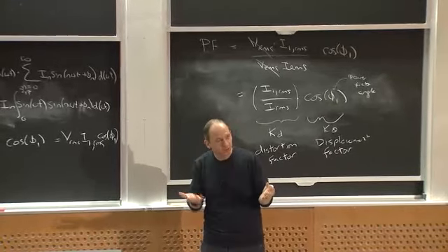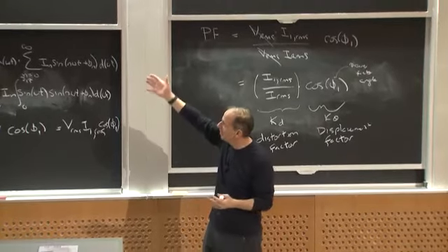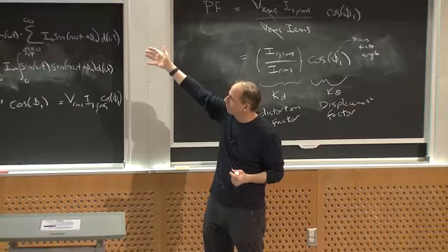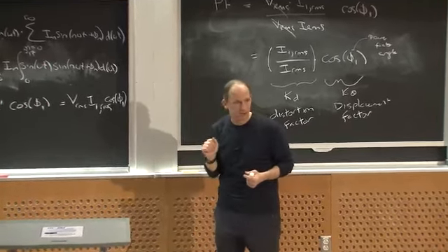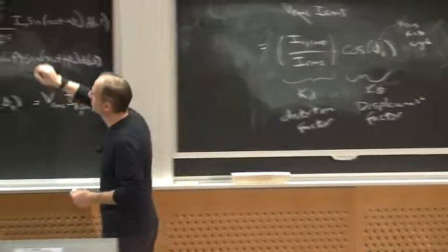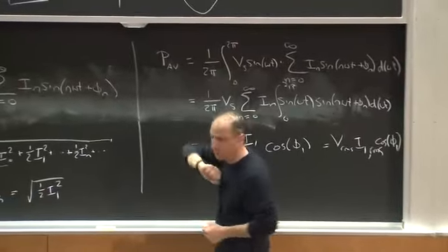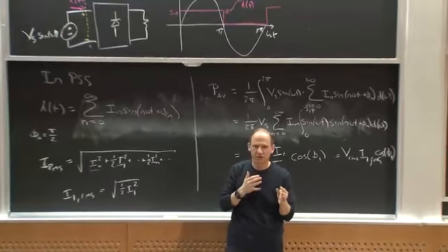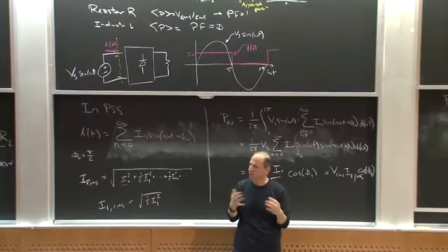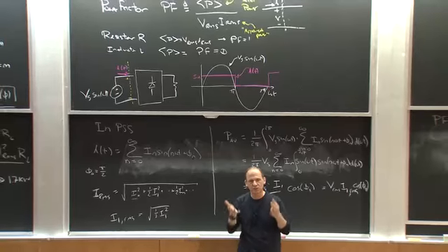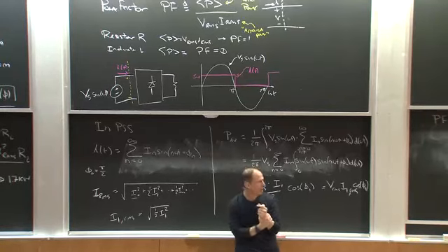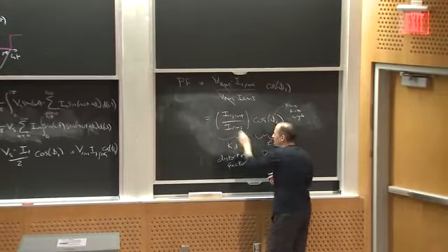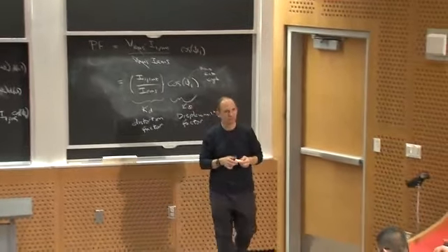Within my 15 amp limit, I have a limited amount of power I can draw with this rectifier just because of the harmonic currents. The fundamental of this pink waveform is actually in phase with the voltage. So I'm not hurting myself by having phase shifts like I did with an inductor or a capacitor. But I am limiting the amount of power I can draw by the fact that there's a certain amount of non-fundamental component in the current waveform.